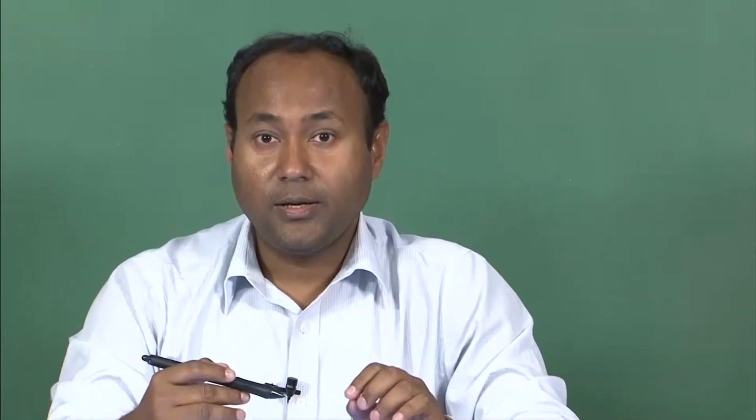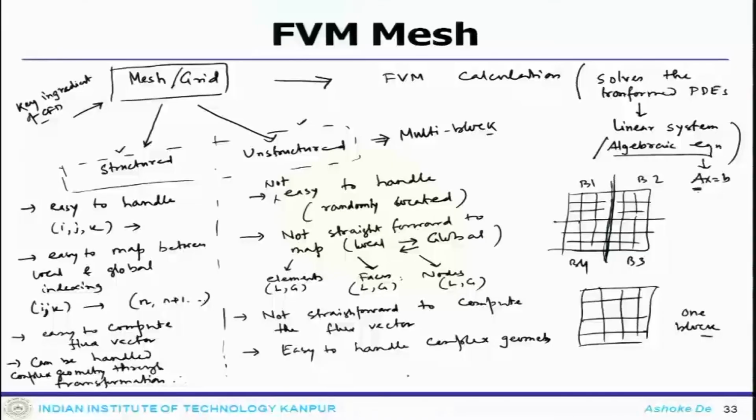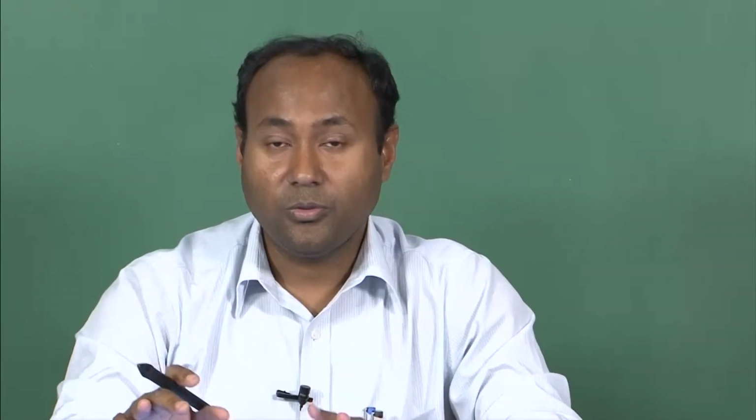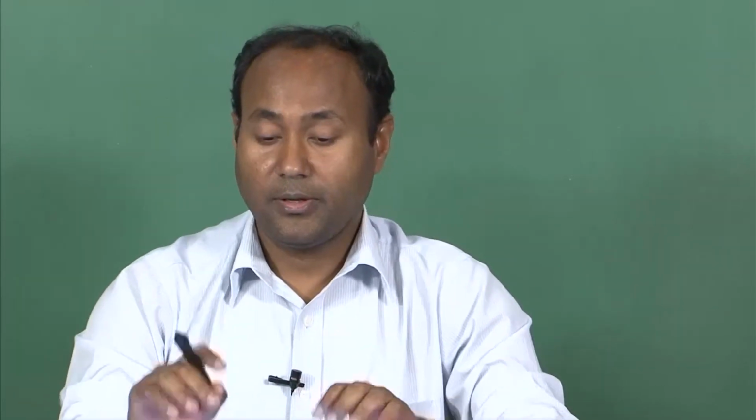For the unstructured system, the calculation of the flux vector is not that straightforward, whereas for the structured system, it is quite straightforward. And having said that, you might have certain kinds of geometry like axisymmetric situations, or when the connecting distances between neighboring centers are not collinear, some difficulties in calculation of these vectors, but this would be discussed in detail when you go down to finer calculations. So, we will stop here and thank you.